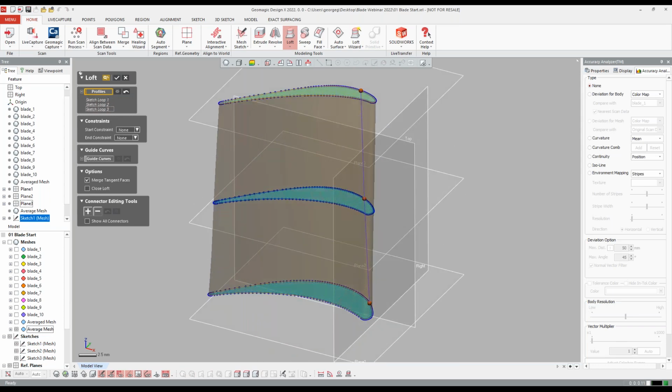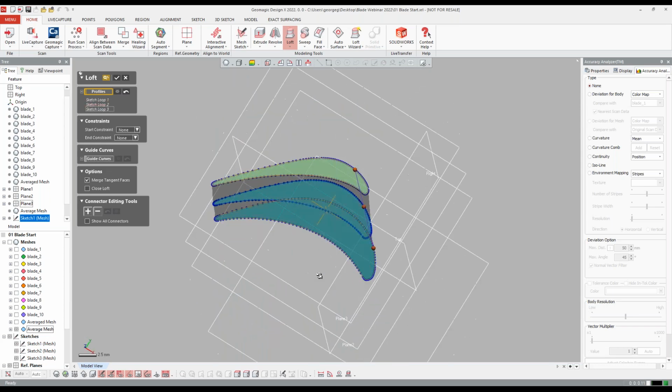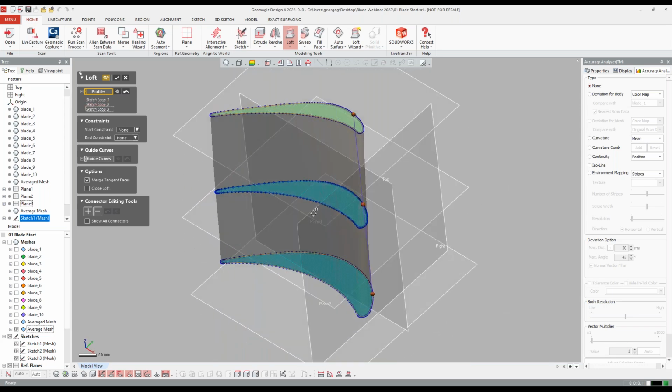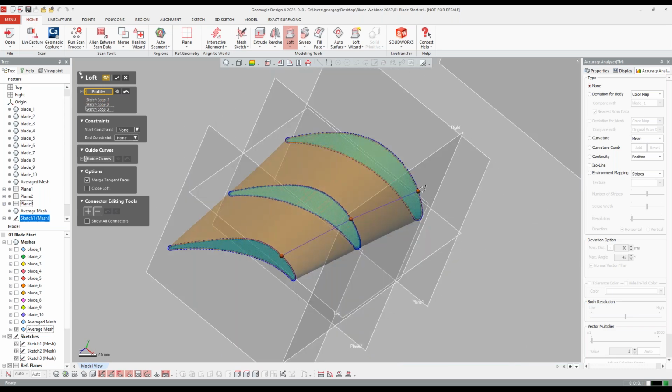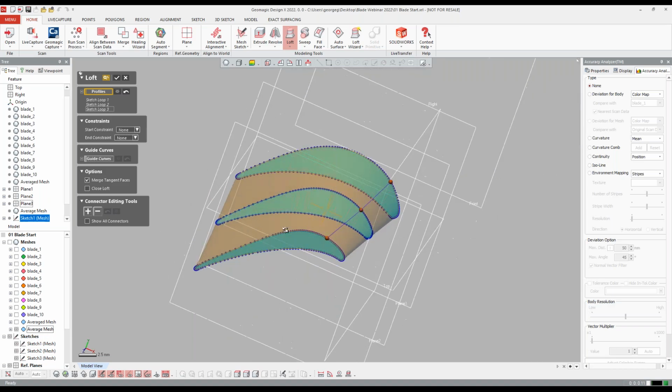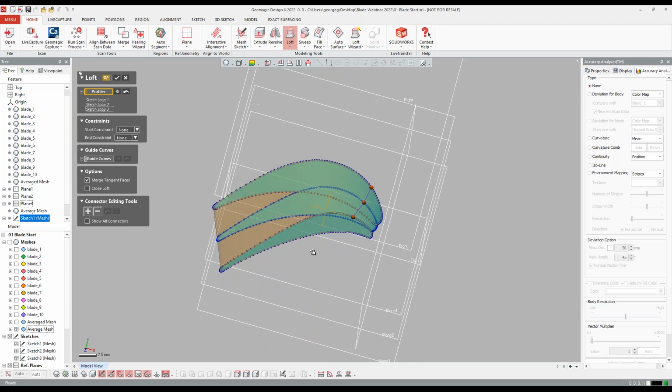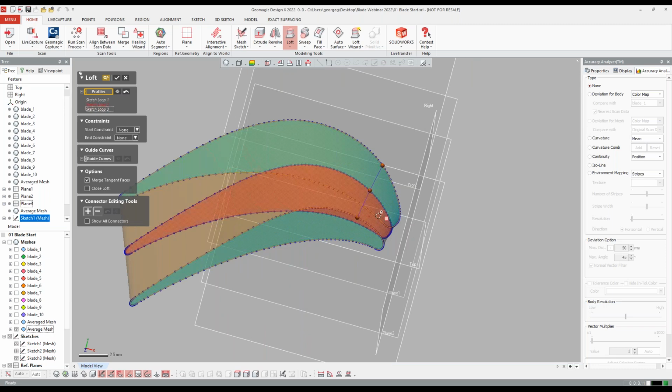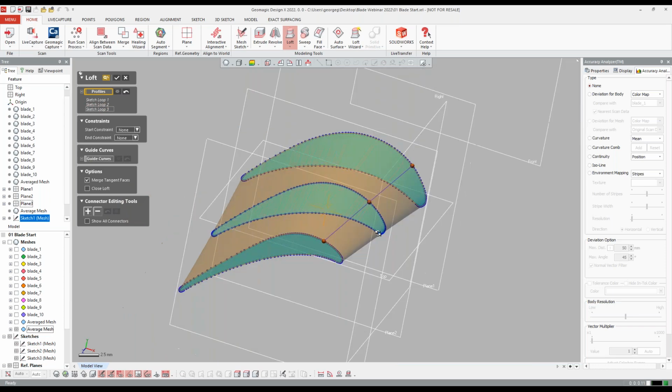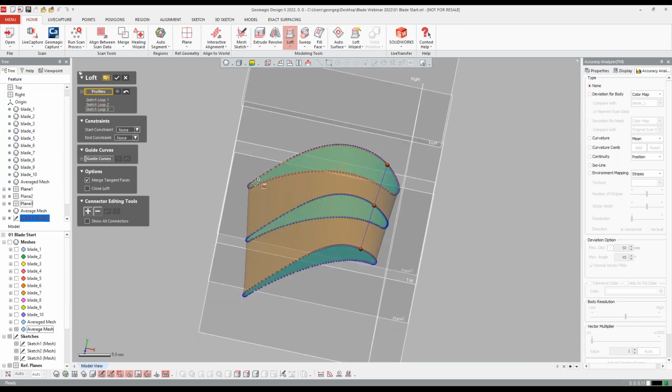And this actually highlights in our lofting tool a new piece of functionality that we've added in this latest version of Design X that released not even a few months ago, right? So we've always had this piece of functionality where we can grab these connectors and align these connectors together. But sometimes you have a very complicated piece of geometry that you may need more connectors than just one. And in the past, what you would have to do is go ahead and manually add guide curves before you come into this tool and use those guide curves as a reference to add connectors, right?